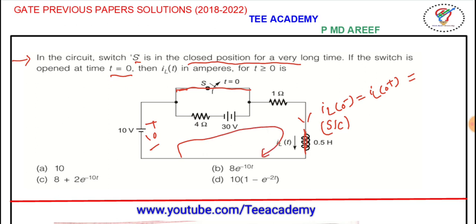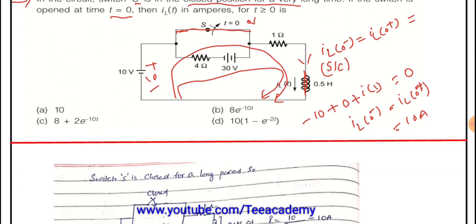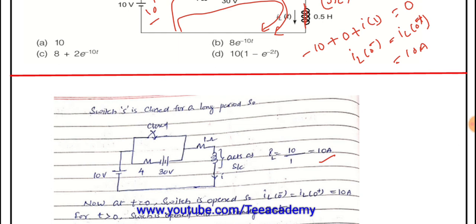and it is short circuited, so directly we can apply KVL in this loop here. Since it is short circuited, we have to use the loop in this direction like this. Short circuited means this will not affect our voltage drop here. So the voltage drop across this circuit is 0 volts. So minus 10 plus 0 volts plus I into 1 is equal to 0. Similarly IL of 0 minus is equal to IL of 0 plus, which is equal to 10 amperes here. So that is what I have written here: IL of 0 minus is 10 amperes.